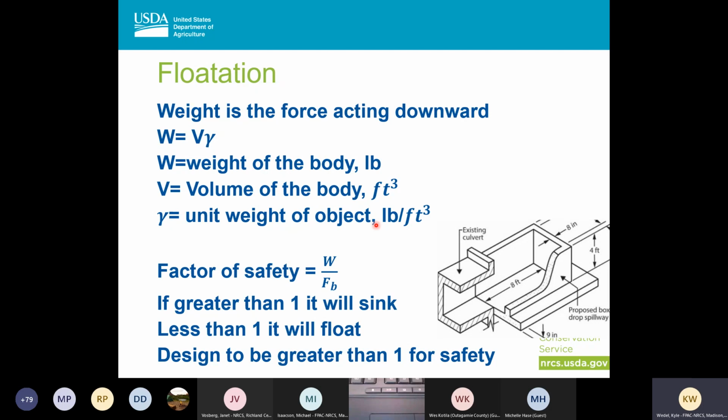When we get that all done, we take our weight and divide it by our buoyant force. If that's greater than 1, it's going to sink. If that's less than 1, it's going to float. We never actually design for 1, though. We always design for something like 1.5 as a safety factor.